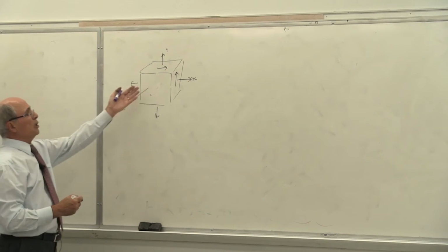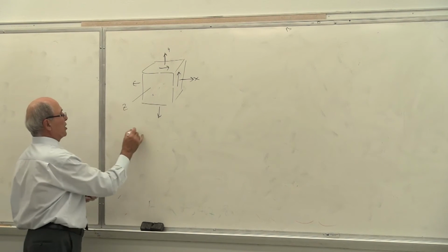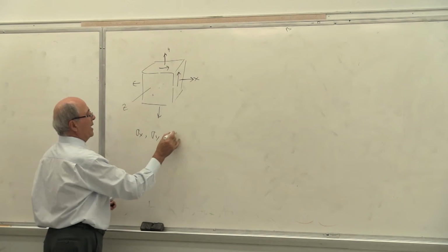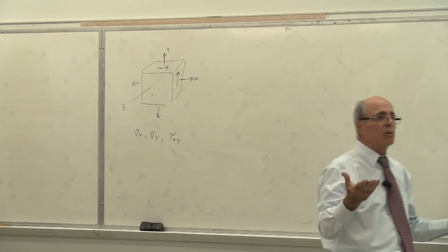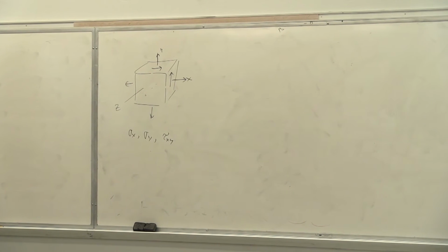Now, we're going to this state of stress, which we have sigma x, sigma y, and tau xy. Notice 3 unknowns. So it refers to 3 equations of equilibrium in 2D. So in other words, it's a 3D object, but we design it as a 2D approach to it. Is that correct? Because we look at all the surfaces. Surface of the shaft, surface of the beam, etc., etc.